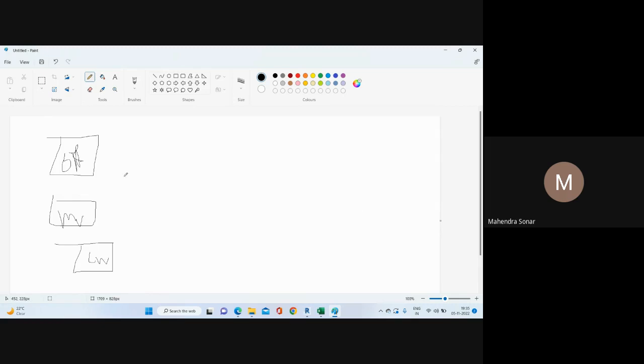So you need to coordinate all disciplines. Suppose you design this pad or plinth, and on this plinth some tank is resting here. Before you start designing the size of this plinth, you need to receive some inputs: weight of the tank, any criteria for this tank, diameter of the tank, volume of the tank. On the basis of that, you need to find out the thickness and sizes.